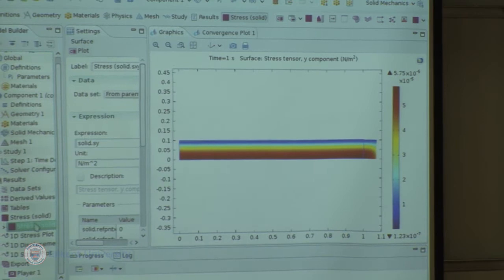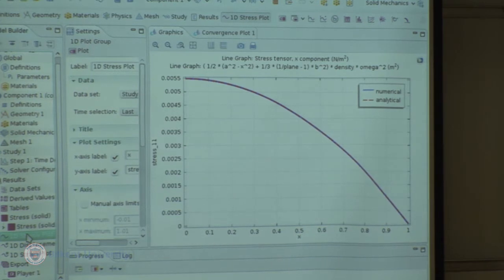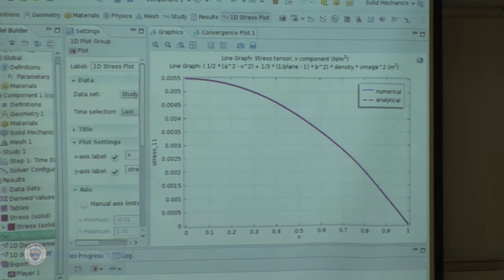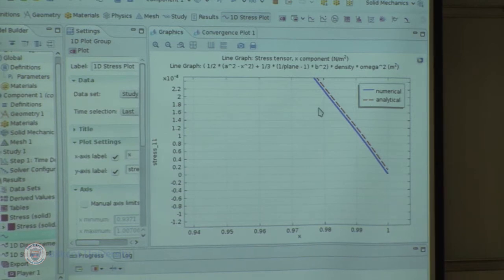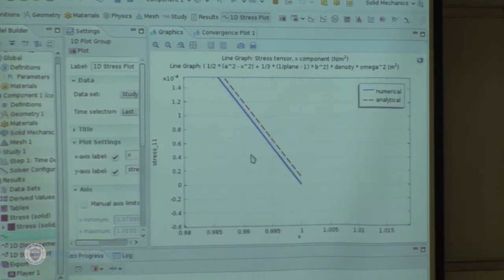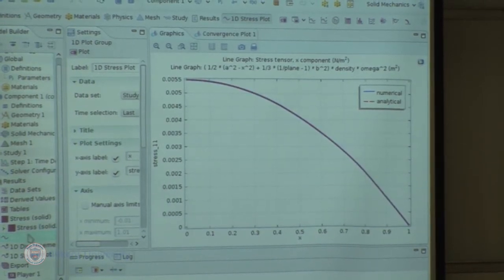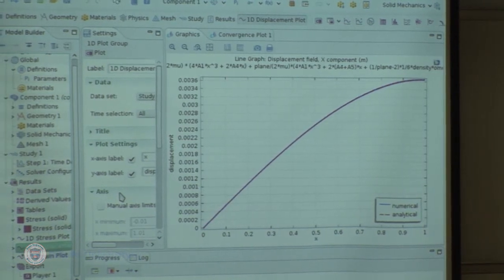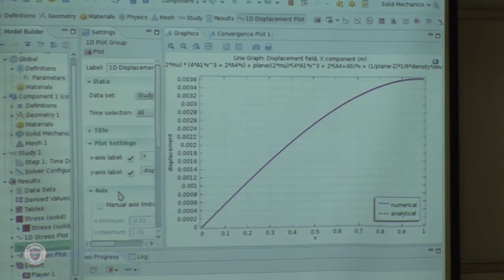And if I go ahead and compare the stresses sigma 1, 1 along x1, x2 equals 0, the match is now virtually perfect. It is not perfect. If I zoom in, the lines will deviate from each other, right? They are not the same, but they are extremely close to each other. So at this scale, you cannot distinguish the 2 lines. And if you look at the 2 displacements as well, they are virtually overlapping with each other, which demonstrates, again, the idea that as the height decreases, all my expectations hold, and I approach the exact solution.